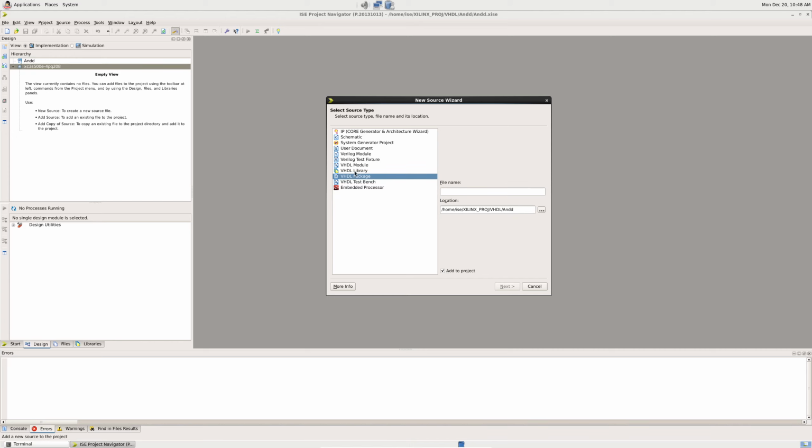VHDL is a little bit more strongly typed, I would say, and also less error prone. You're more likely to have a working solution in VHDL than Verilog. With Verilog, there might be unforeseen errors that you can run into. It doesn't really warn you when things go wrong. With VHDL, you get warnings about pretty much everything that seems off to the synthesizer.